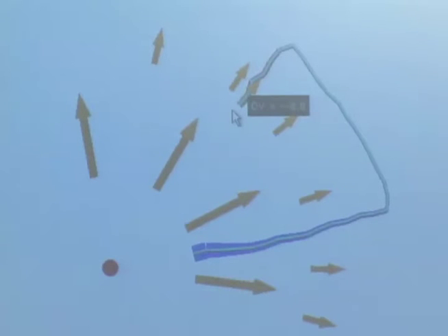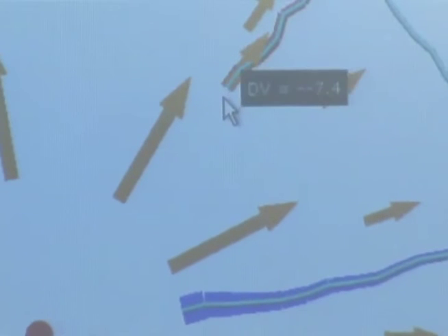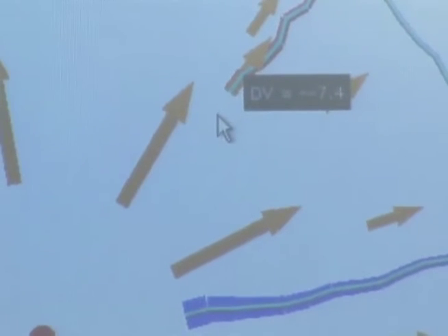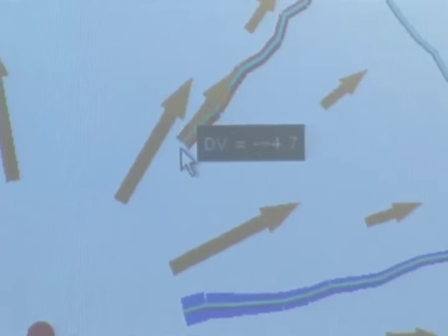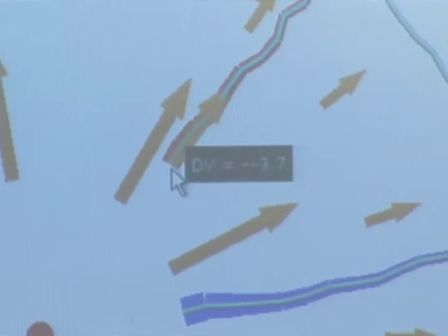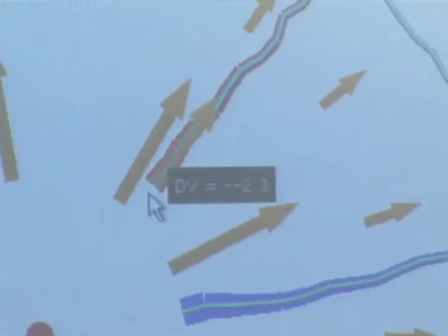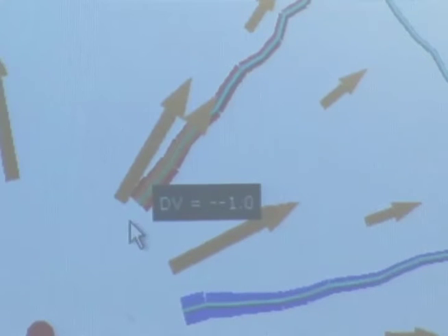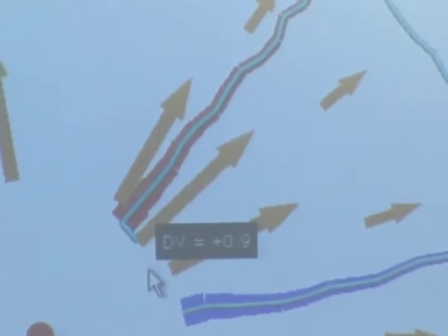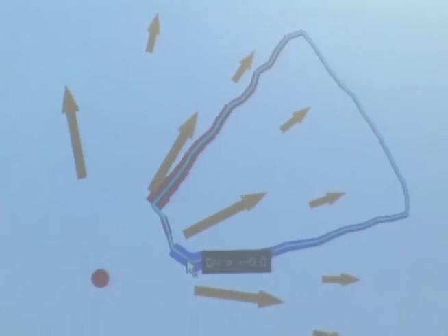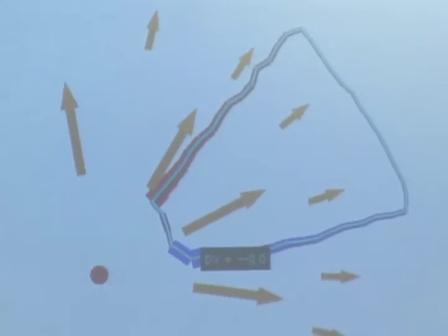It becomes more and more positive because we're moving in the opposite direction of the electric field. So it's going from negative 12 to negative 4.7, negative 3.7 volts, negative 2.3 volts, negative 1 volt or so, about positive 0.7 volts, and then I'll try to close off the path here, come back to where I started, and we go back to 0. Again, sorry if that's hard to read, but it is in fact saying delta V is equal to 0.